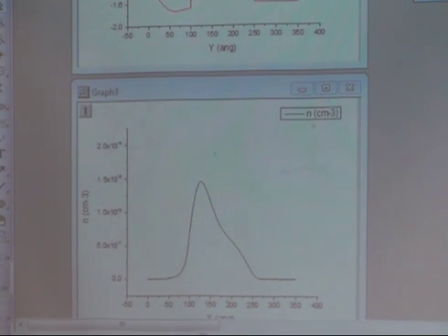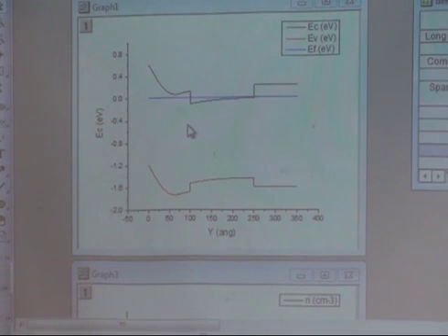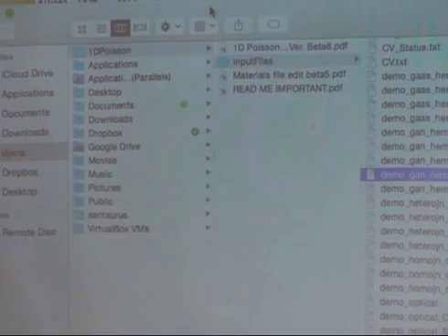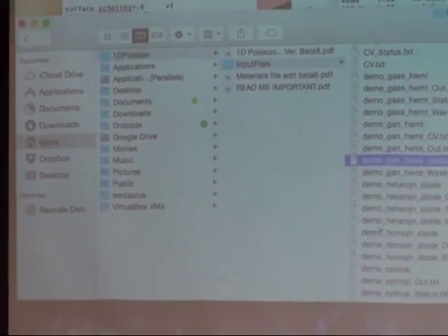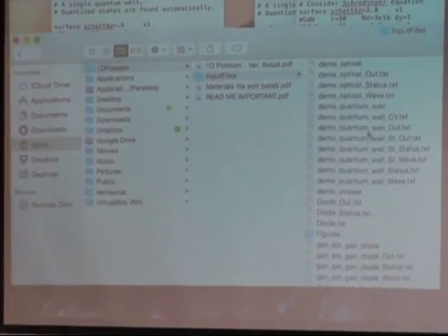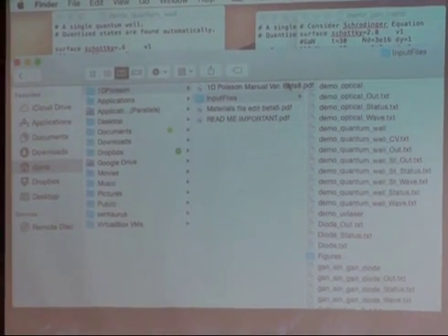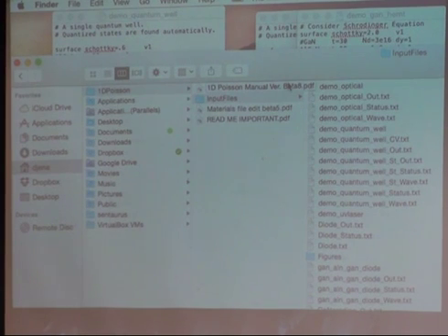Now let's look at an interesting property of this structure. You can go back and look for what happened. Sorry, this screen is a little smaller than normal. What I want to check here is the sheet density of electrons in this well. How many per centimeter square total? What the plot showed you is the volume density, and when you integrate, the area under the curve is the sheet density. Make sense? So that's the sheet density per centimeter square.